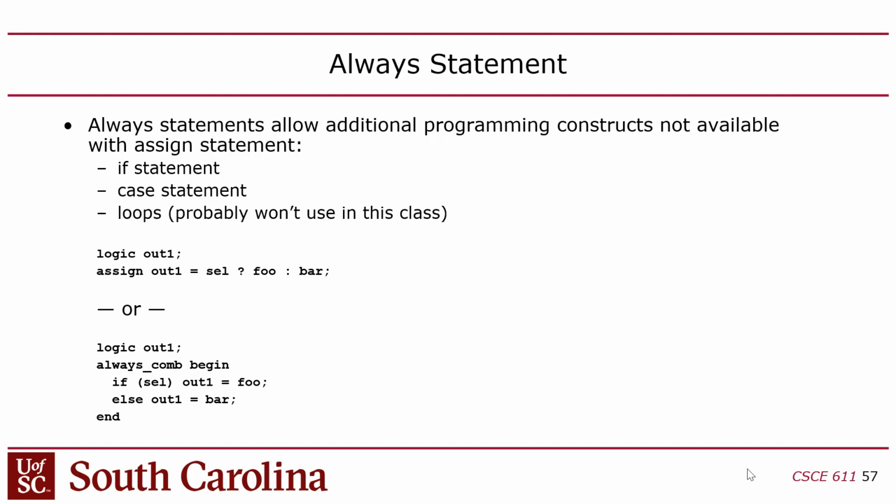Now, the question is, what do you mean by run? Because now you've got an if statement, and you said in the last lecture that Verilog has concurrent semantics, meaning that every line of code in Verilog runs concurrently, and so you can mix the order up of the code and it makes no difference. Well, obviously that can't be true if you're talking about an if statement, because if statements do have an ordering associated with them, right?